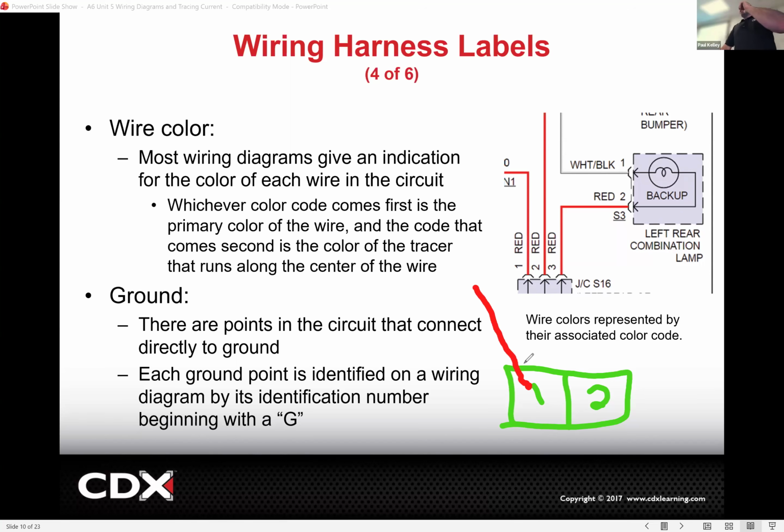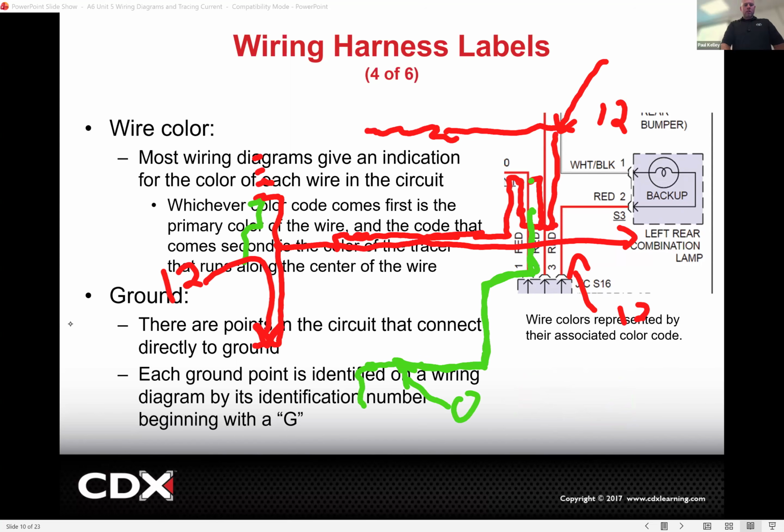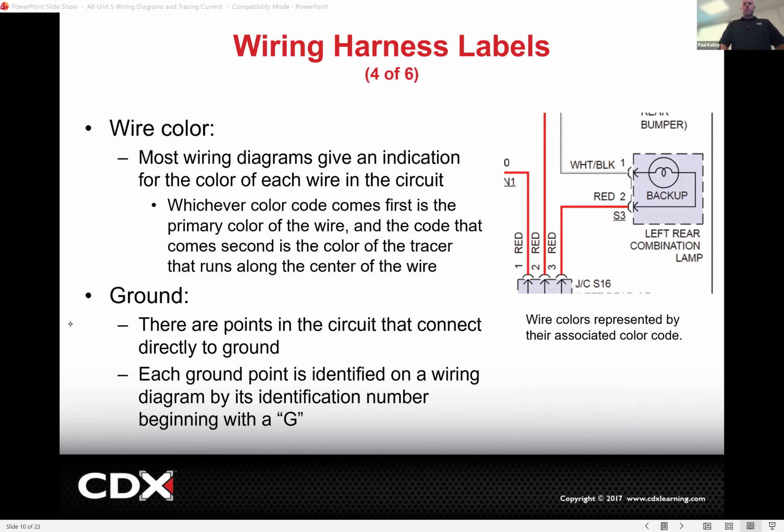We can cover it a bit right now, and then a bit more with wire and terminal and connector repair. And when we get into the unit for lighting systems, you're going to be back probing. So if you understand the diagram, you need one little bit of help where we do the back probe, which just slides right into the terminal. Then you can say, oh yeah, it's got ground, or it doesn't have ground, or it's got what it needs, or it doesn't have what it needs. And that's how you do your diagnosis.